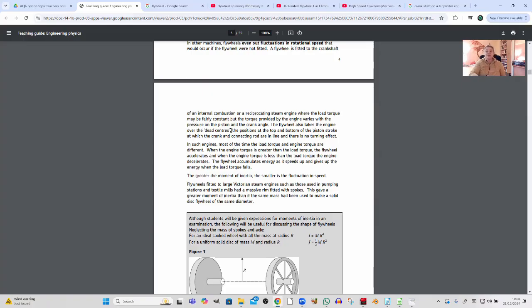Even if you apply lots and lots of force, that's a dead center. And lots of engines have dead centers, especially single cylinder engines. And so you want to be able to push it over the dead center so that it keeps rotating. And that is one of the things that a flywheel does, smoothing out the power delivery of the crankshaft.